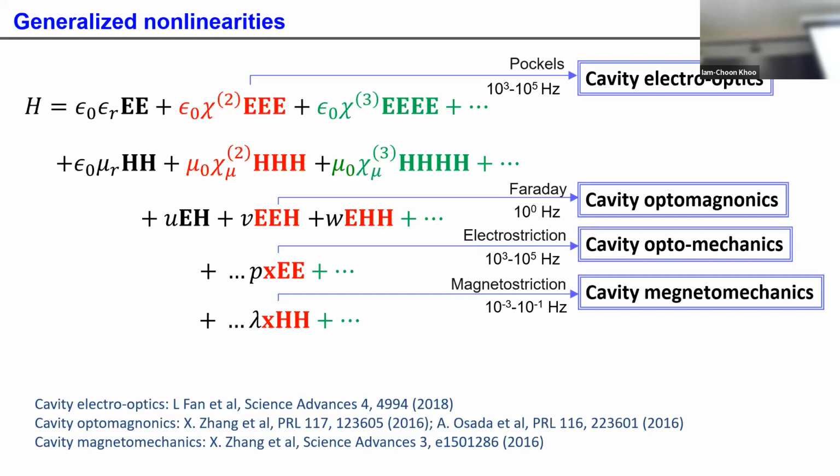That's how we did it for almost 10 years before we did the direct optical approach. I see. A lot of the community, a lot of people, are still trying that. It really benefits from the piezoelectric effect, which is very strong. The challenge is that it's a double conversion, from a microwave photon to a phonon to an optical photon. In the end, the effect is the same, but you have more degrees of freedom to work with. For the intermediate phonon mode, you need to control it to have no loss. Unfortunately, the Q is not always favorable.